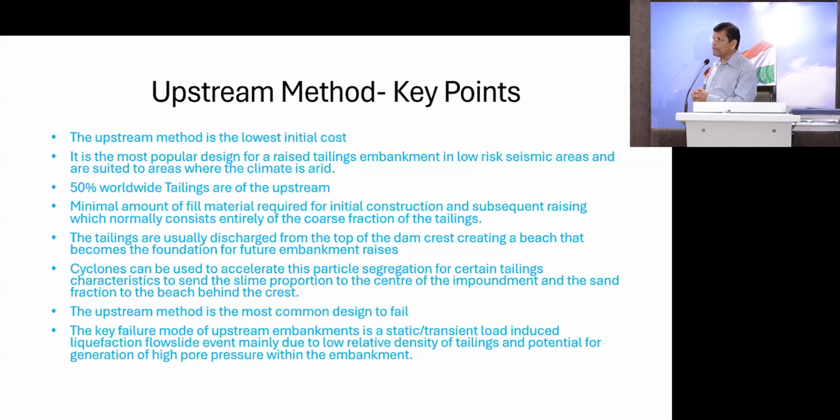But it was found that 60% of the dams which failed are the upstream. So most upstream dams are prone to failure. Even some countries, I don't want to disclose their names, have now banned it, so there won't be any upstream tailings.